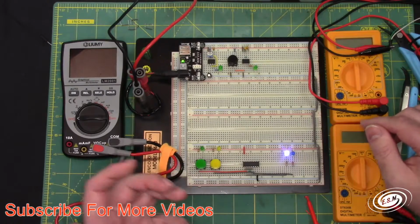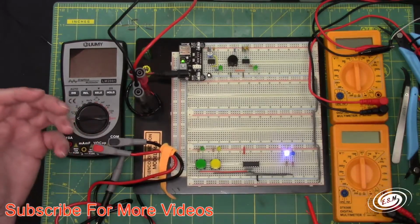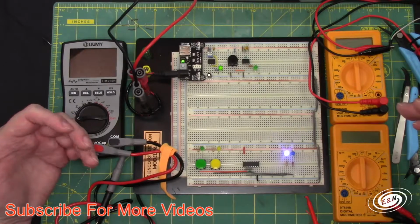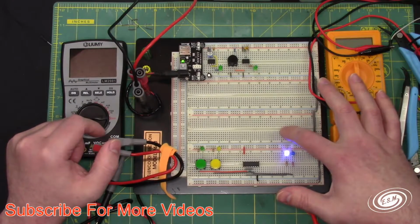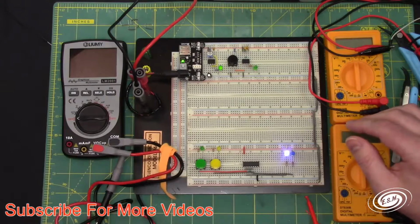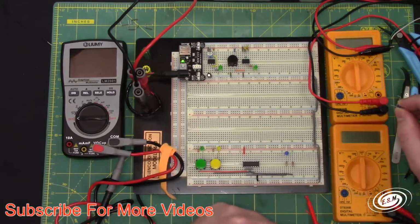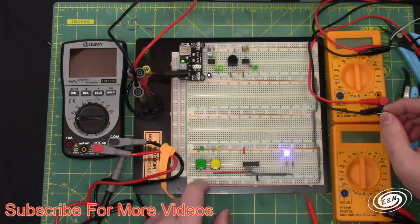So I can press set, I can store a value in there, I could clock it, I could do all different things with a different circuit. Say I was doing a manual shift register, and I wanted to input 1s and 0s. I could hook up the serial data line to the shift register, and when I want a 1, I could press the set button, and when I want a 0, I could press the reset button. So there's set, reset, and you can also look at it like, let's take out Q naught. So now you just have the regular storage register. You can store data, and then you can clear the data. You can store a 1, and you can clear a 1.